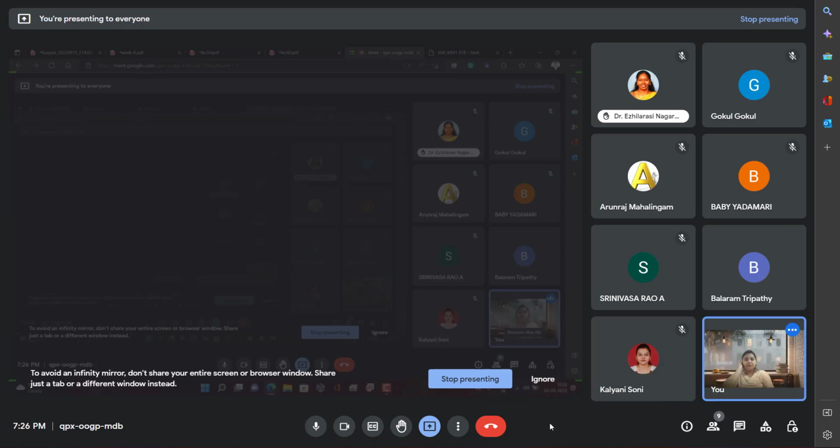So see, there are two kinds of circuit. One is lumped circuit, another is distributed circuit. When we feed this kind of circuit with an electromagnetic wave, either the wave sees this circuit as lumped or as distributed. So what do lumped and distributed mean? Lumped means that the wave has a wavelength which is too big for the circuit element.